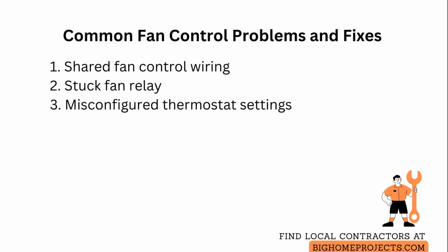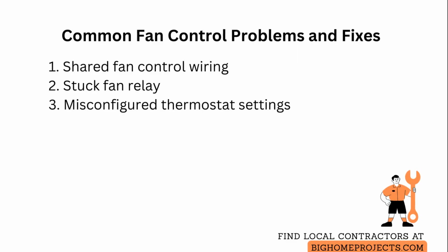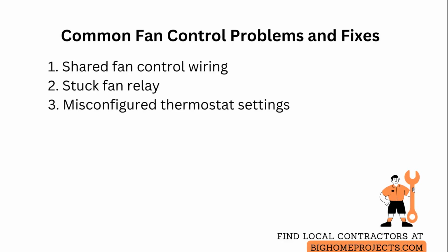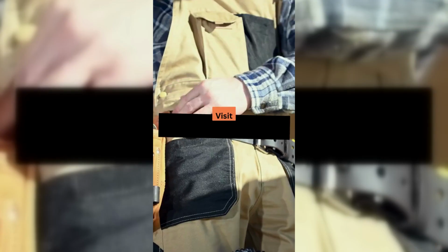For thermostat misconfiguration that forces the fan to run for humidity or circulation, reset the thermostat fan mode to automatic and review advanced settings or disable auxiliary humidity run features. If the thermostat remains problematic, temporarily substitute a basic thermostat to confirm whether the device is the cause.